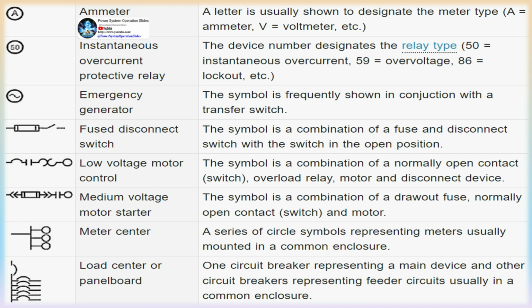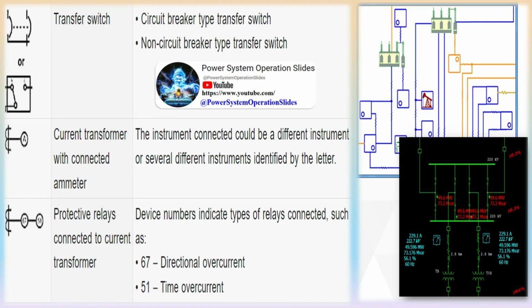Electricity is usually generated in the range of 11 to 33 kV from different sources at a generating station. After that, it is stepped up to either 132 kV, 220 kV, 500 kV, etc. by using a step-up power transformer. Let's say 132 kV. After that, it is sent along transmission lines spread over hundreds to thousands of kilometers. It is received in a station called a transmission substation, where it is stepped down to lower voltage levels. In the above example, it is stepped down to 33 kV.